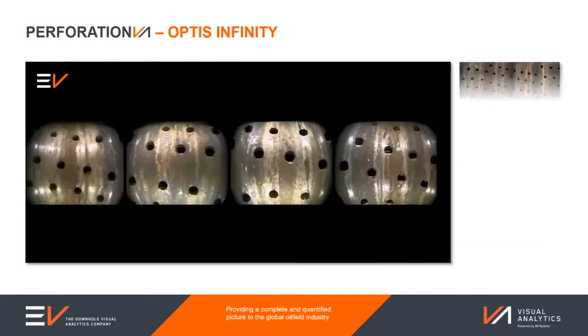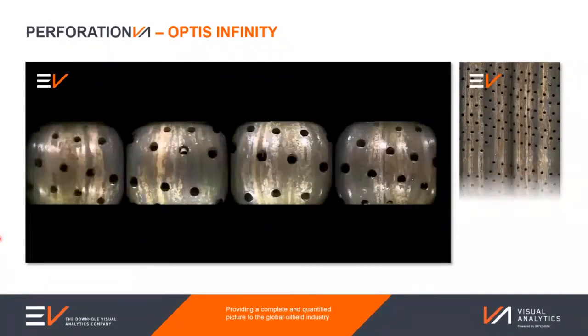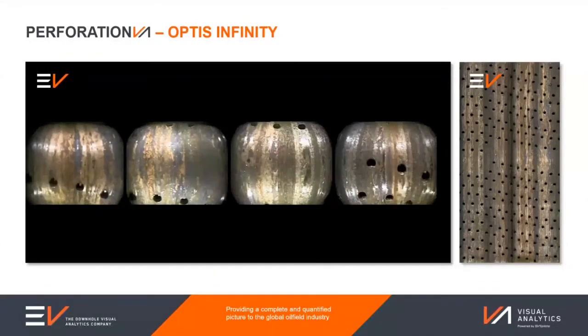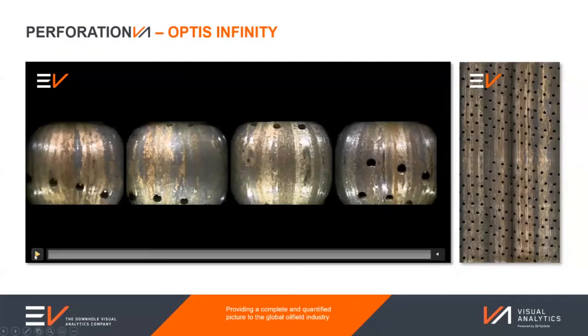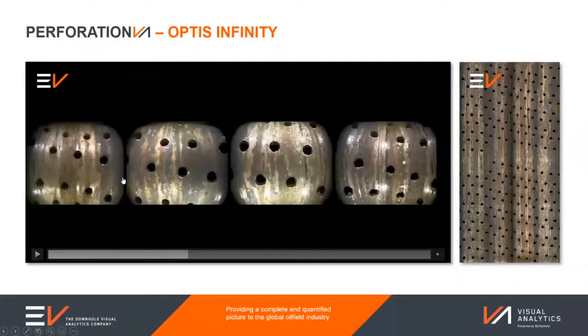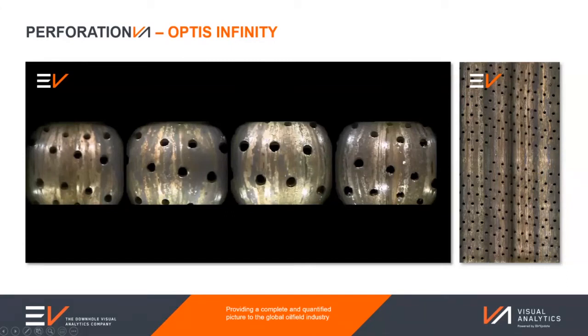Just to give you an idea of what that video looked like, we've got a short video clip taken from the tool, the type of thing you would see at the well site, on the left-hand side here. I'll just play that video clip again. And you can see all 4 cameras and the full field of view that they get. And you can even see where you have overlapping base holes from this screen view. Like this perforation and base hole here is most likely this one here. And likewise, those 2 there are identical. They are the same item. As we have here and here, here and here, there's an overlap in that field of view, which allows us to see a full 360 degrees.